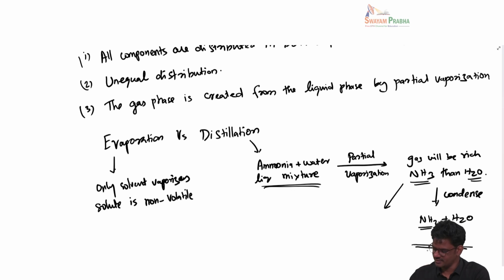Okay, so if I take this particular distillate, and do one more cycle, I take this one, vaporize it again partially, collect the distillate, and look at the composition of ammonia, it will get richer than this solution. And you can think about repeating this over and over so as to get a much richer ammonia solution. But as you do this, you are only partially evaporating.